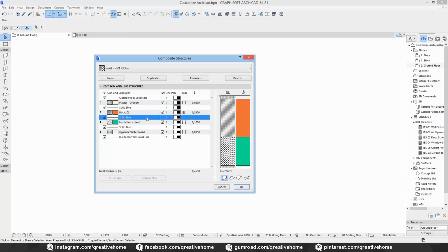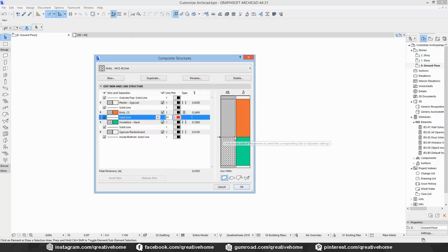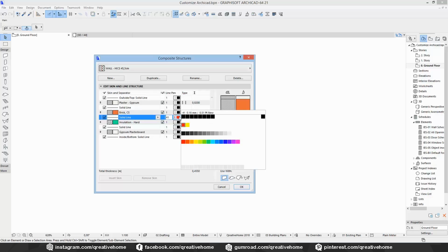This is very useful because there are often separation foils or sealing membranes between some building materials, underneath screed or concrete, or the bitumen sheets on top of a flat roof, for example. In this case, it's useful to have the fitting symbol lines in the line type library. You can also change the color of the lines by changing the line pen.